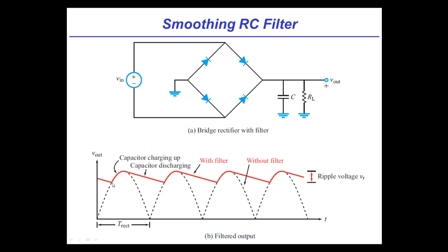What if I just use some sort of cutoff circuit that just says, well, I'm going to reject everything above this point? Oh, so you're saying that it's small enough that last little bit of rejection, it's an inefficiency, but not a very big one. Yeah, I mean, I'll burn this as heat. But if I have something that just sort of burns off any excess over here, it's going to be heat. But if I've got this relatively smooth, I'm not losing too much. Right. And we should say that this is a really exaggerated drawing. Exactly. They never look this crazy. Right. This would be a really poorly designed system if it was this much.